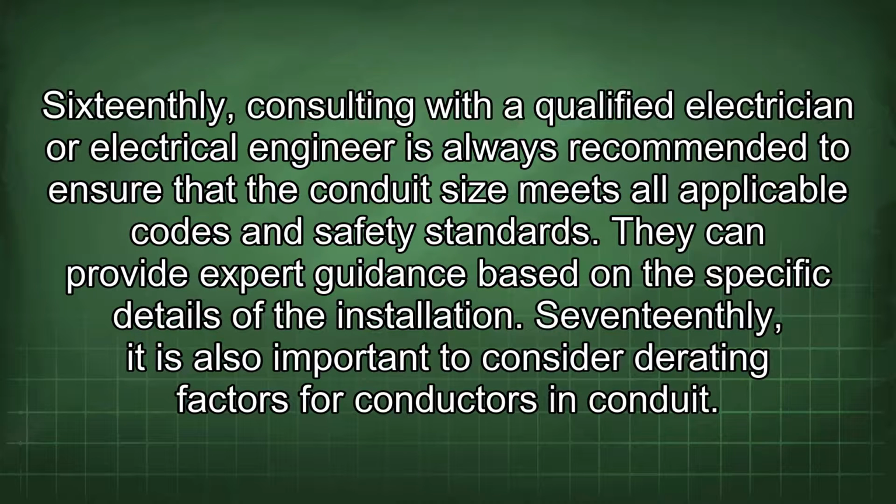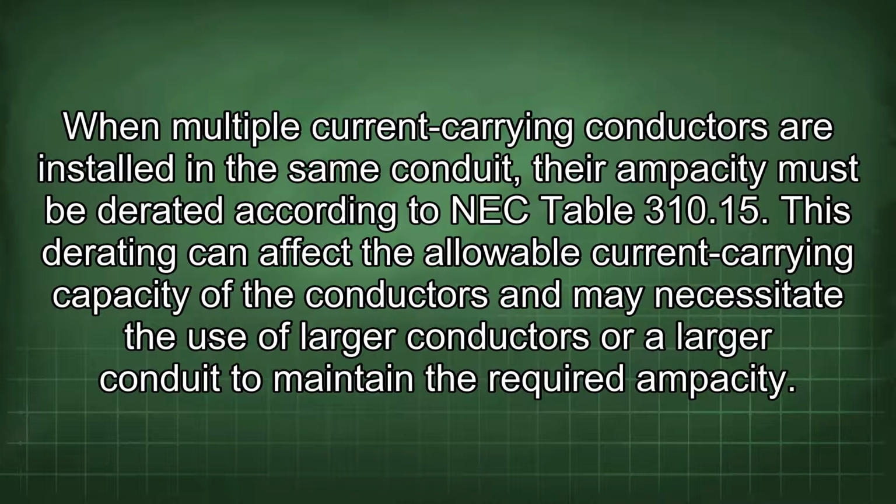16thly, consulting with a qualified electrician or electrical engineer is always recommended to ensure that the conduit size meets all applicable codes and safety standards. They can provide expert guidance based on the specific details of the installation. 17thly, it is also important to consider derating factors for conductors and conduit. When multiple current-carrying conductors are installed in the same conduit, their ampacity must be derated according to NEC Table 310.15. This derating can affect the allowable current-carrying capacity of the conductors and may necessitate the use of larger conductors or a larger conduit to maintain the required ampacity.